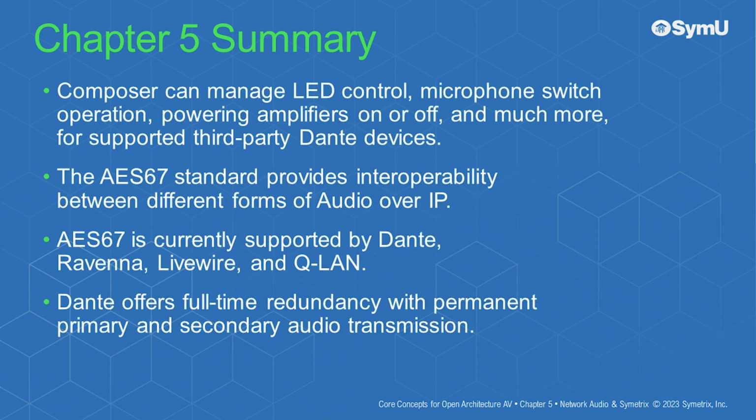Composer can manage LED control, microphone switch operation, powering amplifiers on or off, and much more for supported third-party Dante devices. The AES67 standard provides interoperability between different forms of audio over IP. AES67 is currently supported by Dante, Ravenna, Livewire, and QLAN. Dante offers a full-time redundancy option with permanent primary and secondary audio transmission.